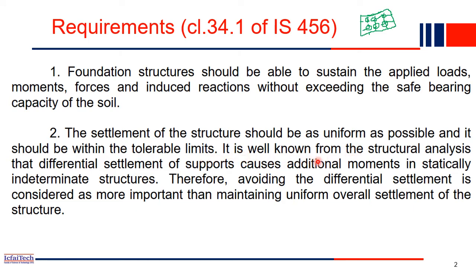It is known from structural analysis, as we discussed in the last structural analysis course also, that because of differential settlement of the supports, additional moments will be generated in an indeterminate structure. That's why we should avoid differential settlement. All columns should settle uniformly, the same amount. Then there won't be any additional stresses on a structure. So these are the two very good requirements you have to maintain while designing the structure.